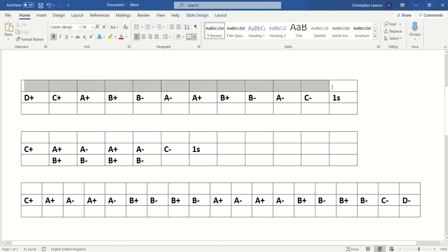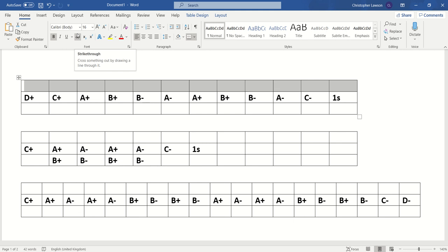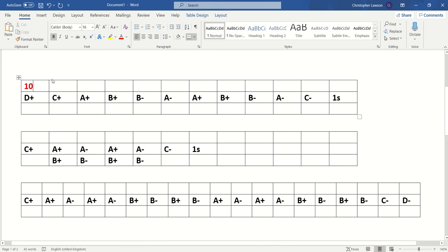Okay, so a step number, so that I can keep track and I can actually fault find it if I do something wrong towards the end. So I'll write these in red. And what I do is I start at 10, because my resting state is going to be 0. So we do step 10, then step 20, then step 30, step 40.